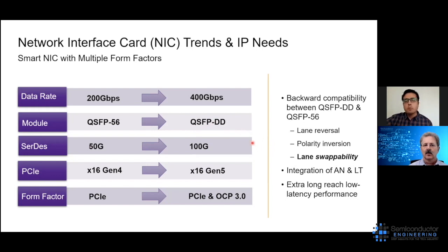Finally, this NIC supports multiple generations of Ethernet. Before this, there was 100 gig Ethernet, there was 40 gig Ethernet, 25 gig Ethernet, and the way the speed is determined is using auto negotiation and link training. So the new generation 100 gig SerDes with their soft logic has to auto negotiate and train its link with multiple generations of Ethernet. So a lot of verification and interoperability requirements have come up. So it's required that the auto negotiation and link training is incorporated in SerDes.